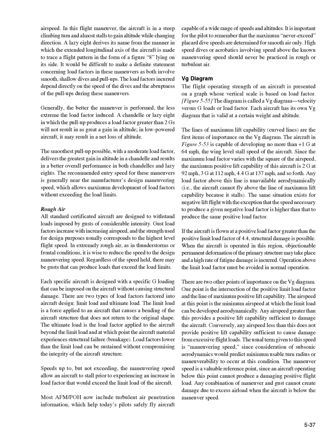In low-powered aircraft, it may result in a net loss of altitude. The smoothest pull-up possible, with a moderate load factor, delivers the greatest gain in altitude in a chandelle and results in a better overall performance in both chandelles and lazy eights. The recommended entry speed for these maneuvers is generally near the manufacturer's design maneuvering speed, which allows maximum development of load factors without exceeding the load limits.